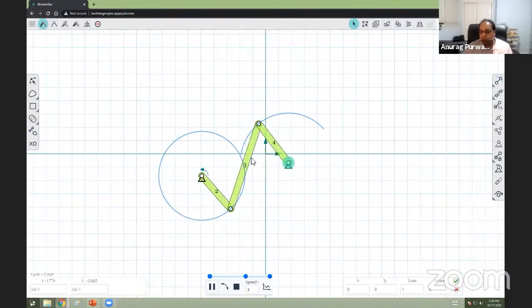It's called a 4-bar mechanism because you've got 4 links here. Now you may be wondering where the 4 links are. I only see 3 links. 3 links are moving. The 4th one, which you don't see, is actually the ground link, or what we call the frame. That link is the one that connects from this fixed joint to this fixed joint. So this is still a 4-bar mechanism. Link number 1, which is not labeled here, is the ground link.